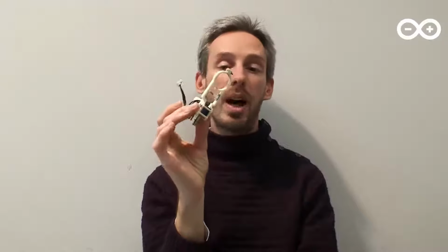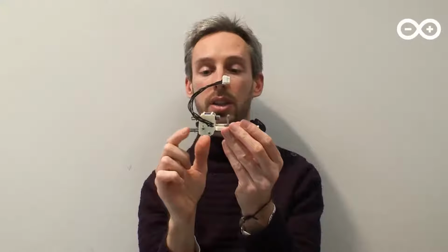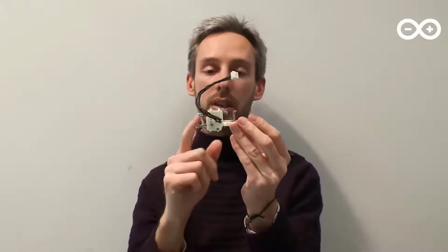So what did I do? I 3D printed in nylon powder a sort of case that can be attached to the central part of the instrument. Why nylon? Because I tried with PLA, but then the 2 solenoids that are hosted in this structure got so warm that the PLA started to warp and to melt.